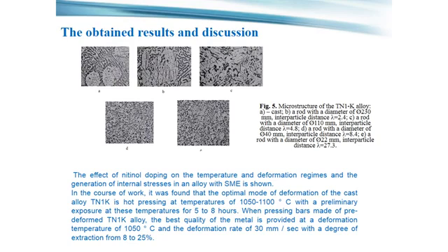The high characteristics of the parameters of the titanium nickel based alloy, its shape memory effect, such as the degree of recovery, the developed forces, the amount of accumulated reversible deformation with increased plasticity, and high corrosion resistance, determine the prospect of its wide application in engineering, ensuring high and stable thermomechanical characteristics of titanium nickelide in specific devices over the entire operating temperature range, and the ability to vary the parameters of the shape memory effect and superplasticity